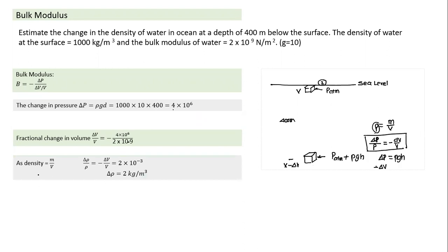And then how do we get density here? Density rho is equal to m by v. So delta rho by rho is equal to minus delta v by v. I have delta v by v from here, and negative of that. What do we understand here? As the volume shrinks, density has to increase, which makes sense. Since I know the value of rho, I can find delta rho.